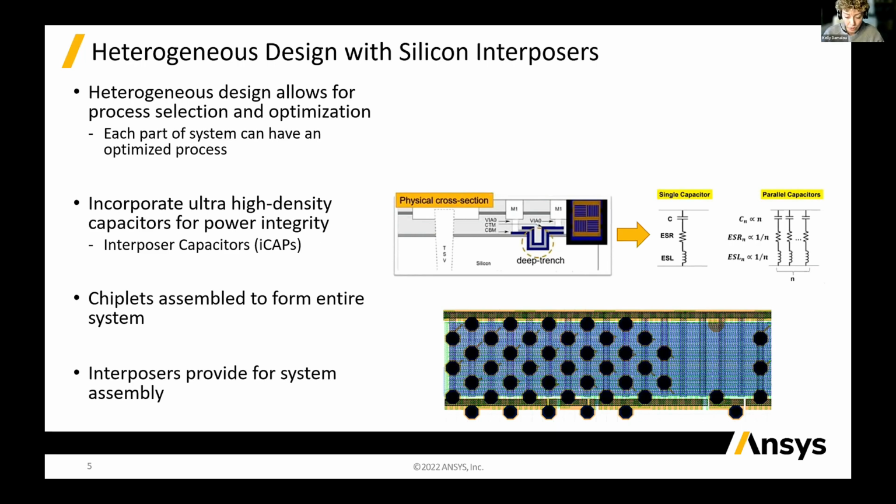An important feature of multi-die 2.5D IC assemblies is the interposer, which carries the signal and the power interconnect between chiplets. Interposers are most typically implemented as a large silicon chip with interconnect feature sizes based on mature process nodes like 65 nanometers. High-speed digital buses transfer information between chiplets, including high-performance graphics accelerators, network controllers, I/O blocks, machine learning chips, SoCs, and high-speed memories. So, all sorts of chiplets.